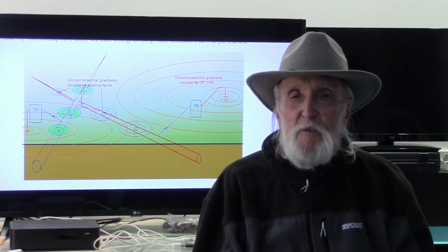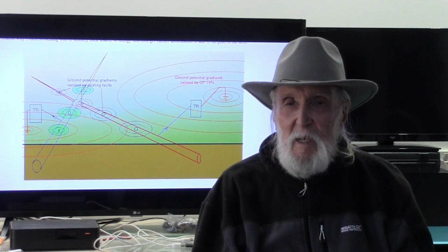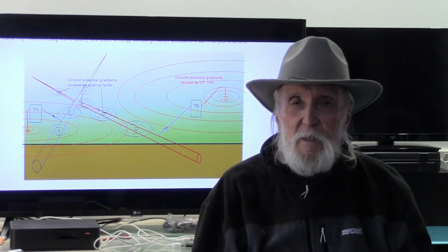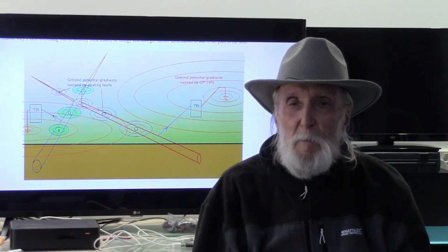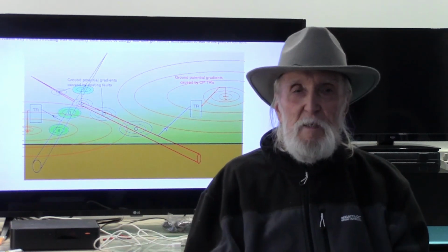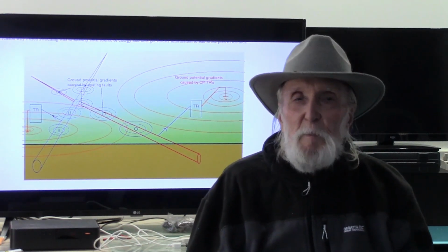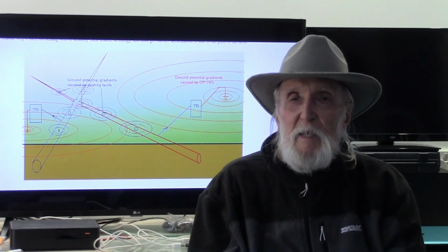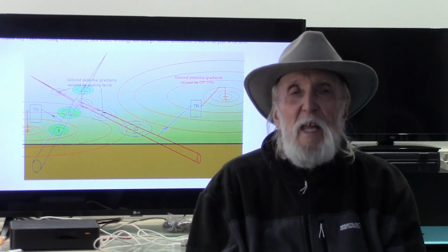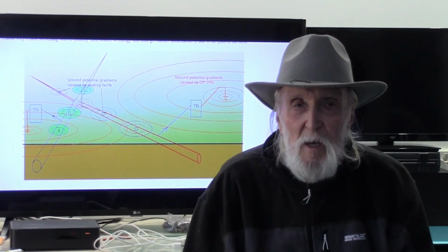Accelerated corrosion is readily prevented by the exact placement of sacrificial anodes, which must be provided with a method of continuous monitoring. This is simple to carry out, providing you have a clear perception of the electrical picture.